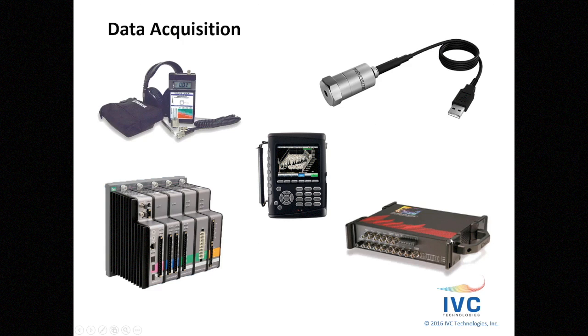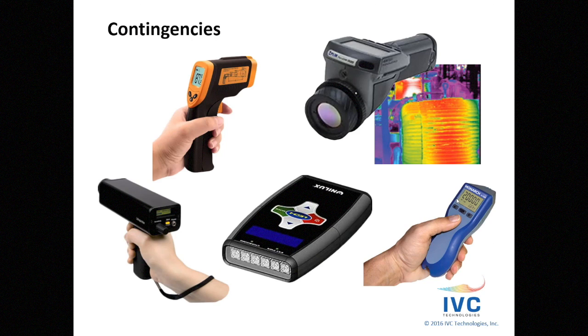And then in the bottom right, this is your typical scalable, semi-luggable rack mount type data acquisition system where you can add additional modules and go from 8 to 16 to 56 to whatever your necessary channel count would be. Depending on what you need to accomplish the test, that's really what's going to determine what type of data acquisition I need to bring with me.